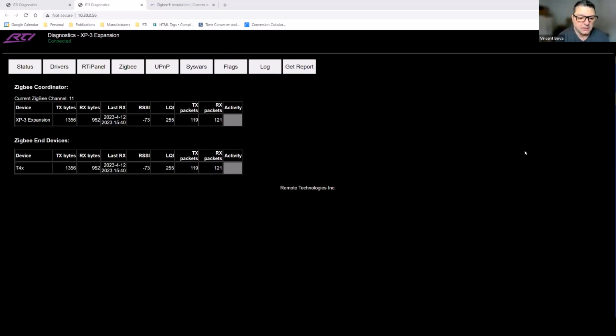That could cause packet loss, therefore an LQI that is unsatisfactory. So make sure that the LQI is in the 250 range. 255 is ideal. And if you start to get wacky numbers, start to question if you have some cross communication going on that's interfering. Let me give you an example of that in my own house.